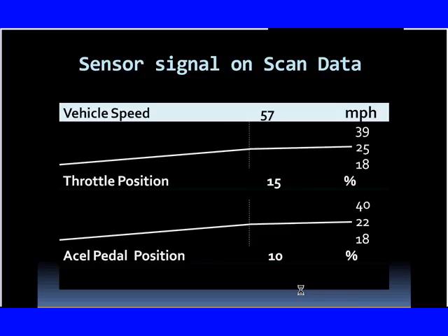Okay, remember the accelerator pedal is the driver's input. The throttle is the result of the computer deciding that input is valid and moving the throttle. So that is going to be one of the things you'll be seeing as you look at scan data. You'll look and it's a decision that has been made to move the throttle. Just keep stressing that factor.